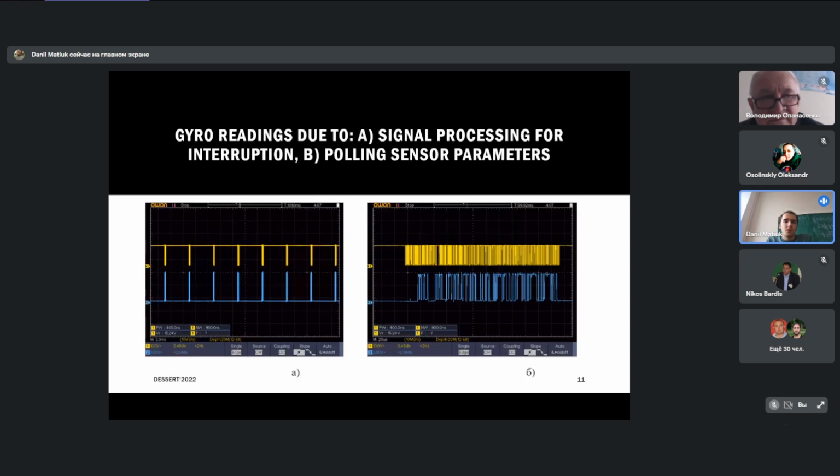For data exchange between the STM32 microcontroller and the GY-521 module, we developed a method for connecting the device via the I2C interface. Verification of the development method for reading data from the sensor register was performed as follows. Interrupts occur about 45 times per second. Each interrupt lasts about 22 milliseconds. 14 sensor indicators are processed in one interrupt, respectively at address.